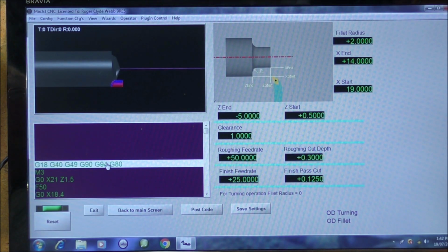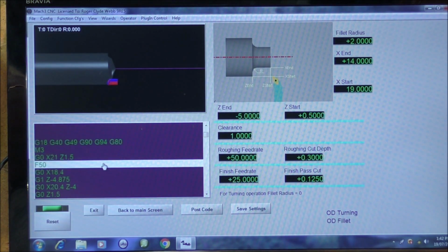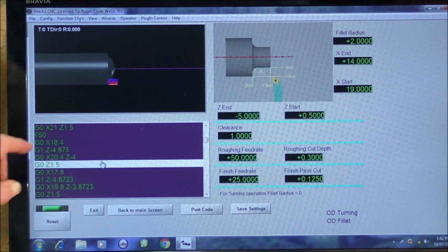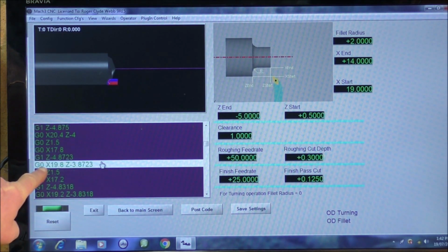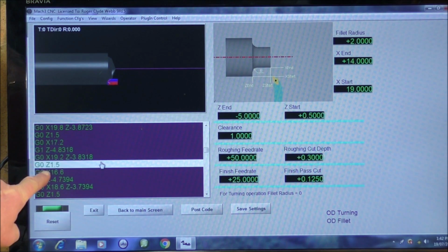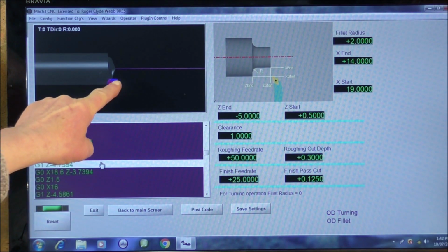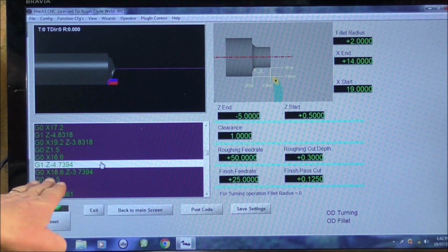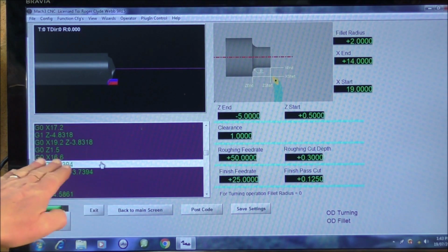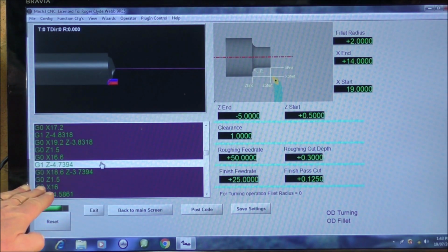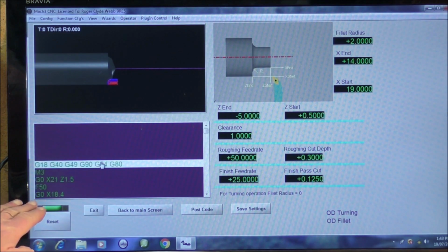Also here, if you highlight this box, you'll notice in Mach a little white line come in relation to where you are in the code here, so you can follow through and find out exactly where it represents in the code. The code actually represents the actual motion, and this is a very good way of learning G-code, or even how to write it. This opening statement here is just setting up Mach3 to known values.